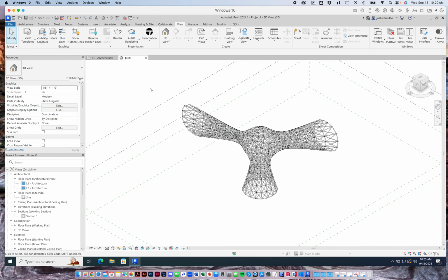All right. Now, what do I need to do? I need to reestablish the grid, right? We talked about that. With Revit, it's really important. I mean, one of the first things you usually do is get the site in here, and then establish the grid. We are using no site, but we'll worry about the site first. But what we need to do now is reestablish that 15-foot, 15-foot, 15-foot grid.